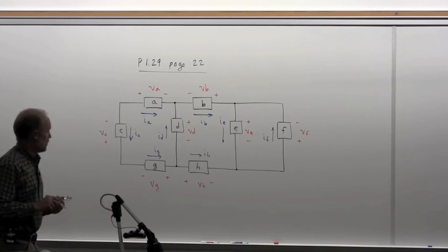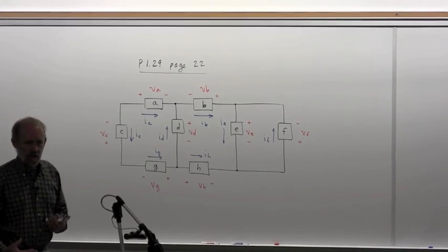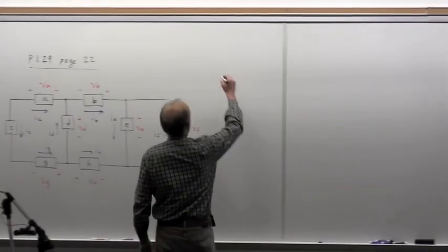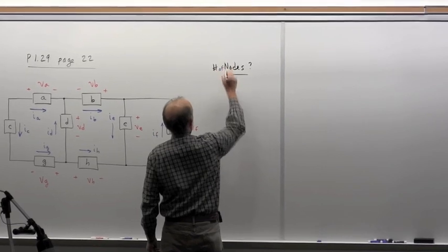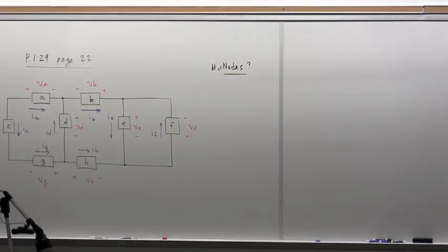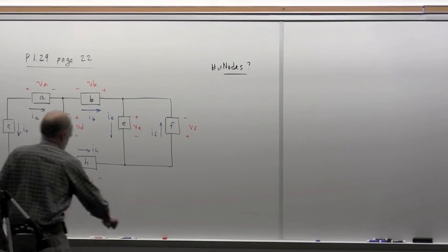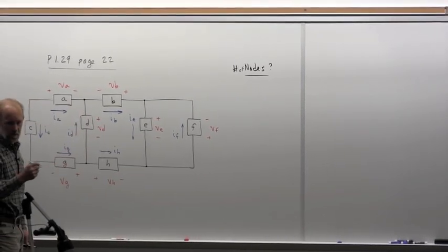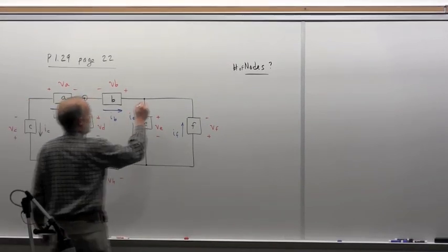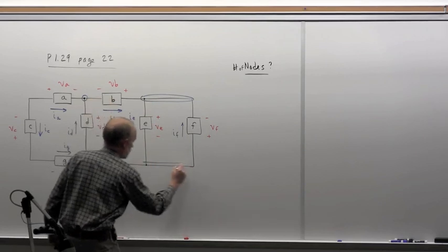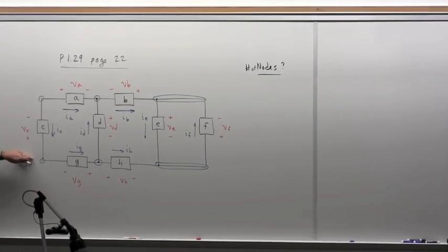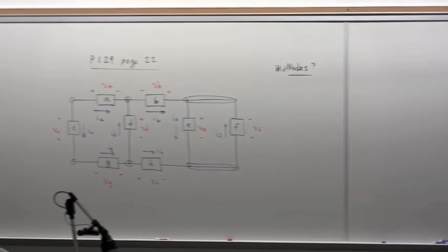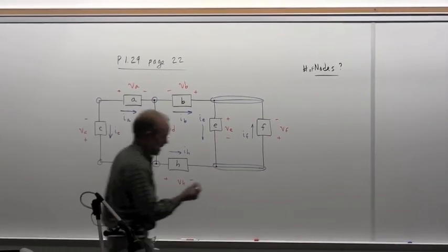Okay, so while we have an opportunity, let's go back to some of that circuit terminology. So how many nodes do you see in this circuit? Okay, sounds like the consensus so far is 6. So let's just quickly look at the points where 2 or more elements join. That's how a node is defined. So we've got one there, one there, and then don't overlook, based on our definition, that this is a node and this is a node. So yeah, those of you that were indicating 6, that is the case.